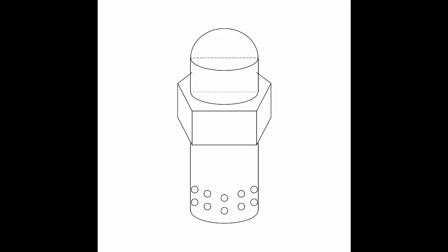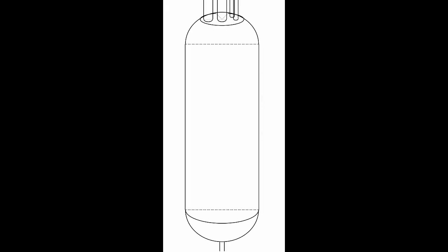The complementary burner systems is the basis of the adaptation of the biofuels burn power supply of prior presentations as in the picture. However, an industrial bioreactor size conformant design as shown was adopted for the design of the small farm's anaerobic digester. By the design, the digester bioreactor is a cylindrical vessel with oblated spherical cap at the top and bottom. The top cap is fitted with an axial stirrer and a thermometer, a pH meter, mixture level sensor, and a feed port. The bottom cap has an outlet pipe for emptying the contents and digestate at the end of each batch operation.